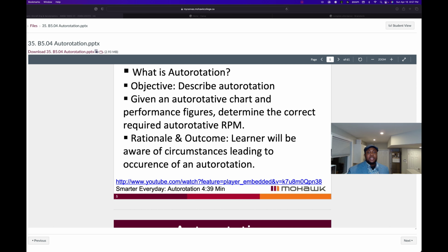Each in abnormal positions about their vertical hinges. Another name for the vertical hinge is the drag hinge or the lead lag hinge. So when these blades lead and lag, if they bunch up together, this can cause uneven distribution of the center of mass. This is what it looks like, this image on your left here.